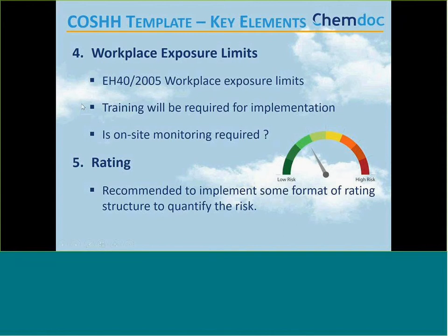It's probably one of the more complicated parts of the COSHH assessment, but it is quite key, because if your product has a workplace exposure limit, then you need to look at how much of it are we using, and ultimately, do we need to get some industrial hygiene monitoring or on-site monitoring in to see if it is safe in here for that? So it is one of the more technical parts of the COSHH assessment, and is the one part that you would certainly need to be a fully trained COSHH assessor to decide.